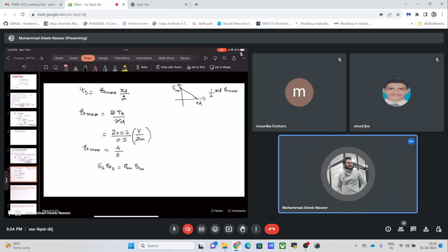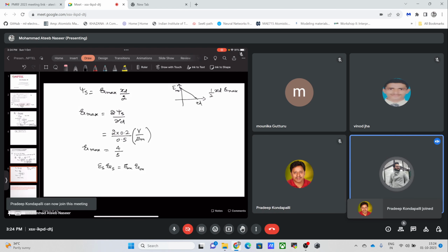This we know, because the electric displacement has to be equal on both sides. So as a result, we have this relation: epsilon s times the electric field in the semiconductor will be equal to epsilon ox times the field in the oxide.